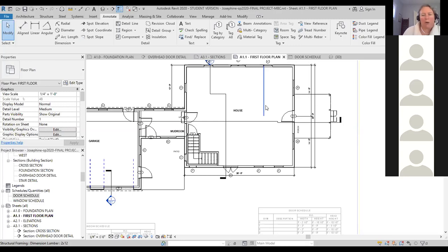And even if you're in a ballpark for what's the widest opening you have, let's say you're picking out some windows and you're not sure if you want them to be a bay window or two double hung windows, whatever one's the largest one, pick that one, and that way your header has been designed for what could possibly be the largest or widest opening, okay? So if any of you are having trouble with how to come up with that window width, that's what I want you to do, just imagine what these windows could be configured like, okay?